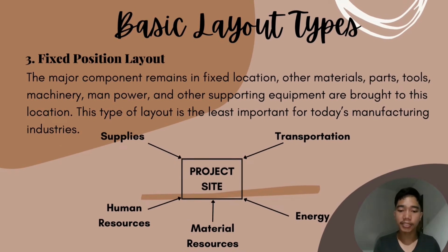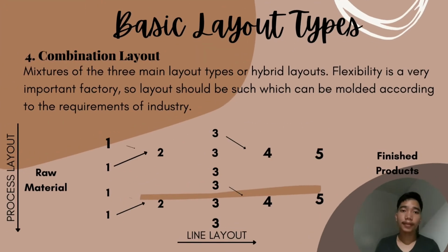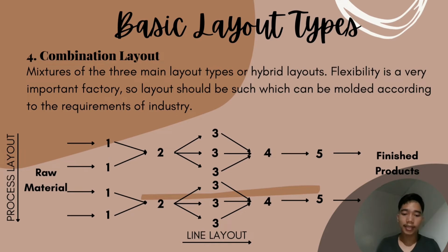Third, fixed position layout. The major component remains in a fixed location. Other materials, parts, tools, machinery, manpower, and other supporting equipment are brought to this location. Fourth, combination layout. Mixtures of the three main layout types, or hybrid layouts.